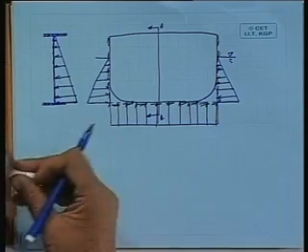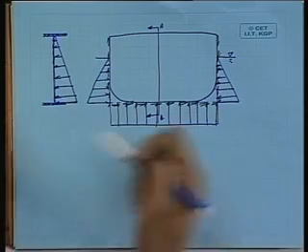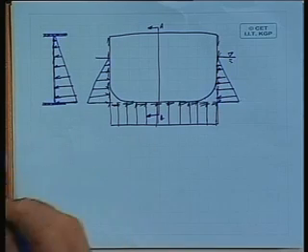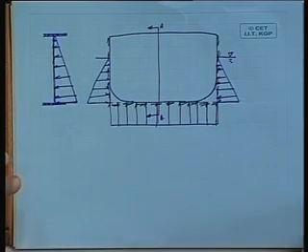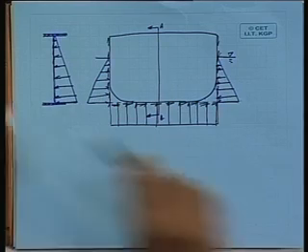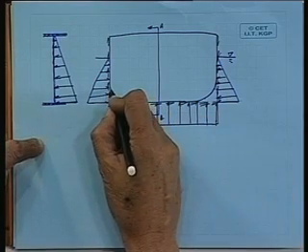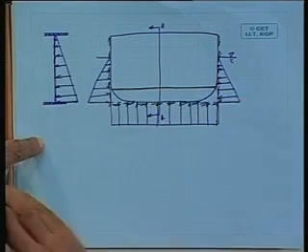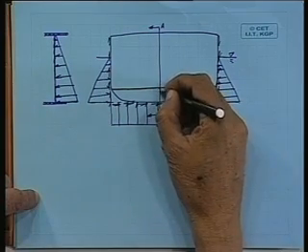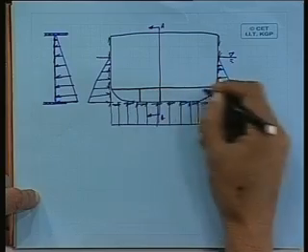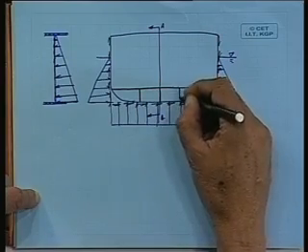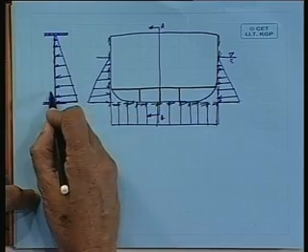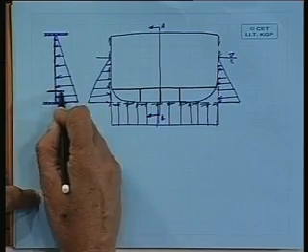Now, this is the load which we have seen, but if you see the construction, then usually what we will find is that somewhere here you will have a double bottom, a usual construction technique. Within the double bottom you will have certain girders here, and the bulkhead; this is the inner bottom.